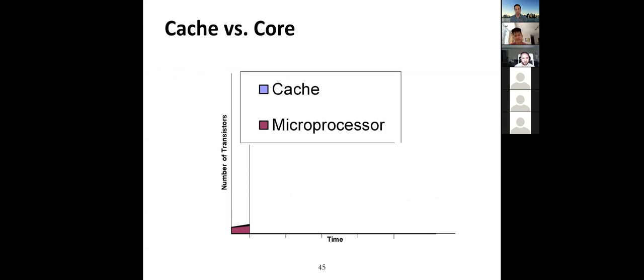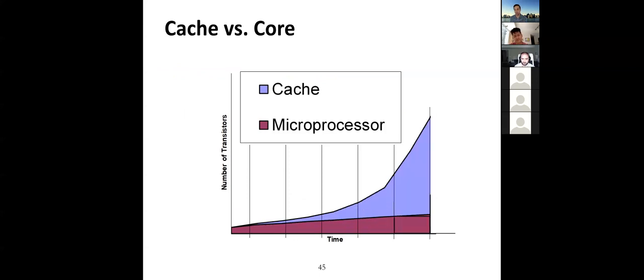In a very coarse-grained picture, at the beginning I just keep increasing the number of cores, and I also want to increase their caches. At some point, the caches needed to support these multicores reach a level where I cannot do this anymore. So instead of spending transistors on caches, I start to spend them on more microprocessors. I'm going to show you some designs of existing chips. You're going to see visually that easily 40 to 50% of the silicon is spent on the caches.